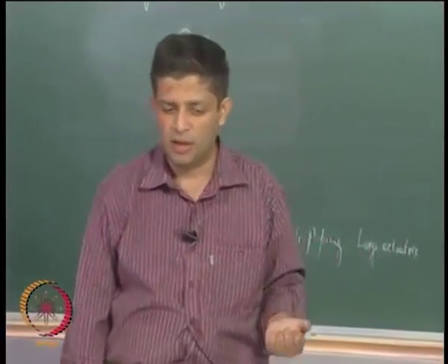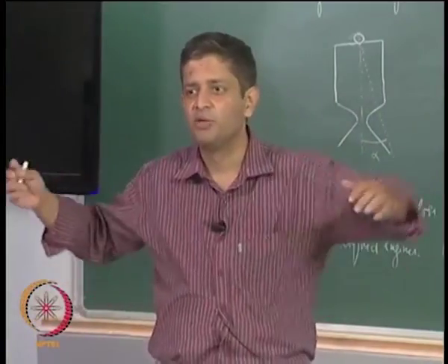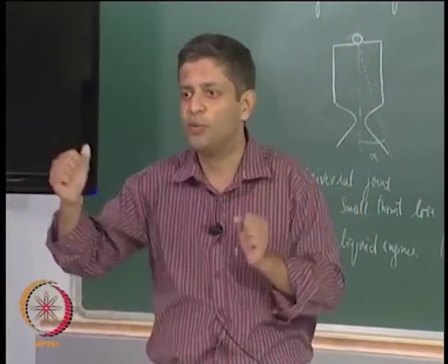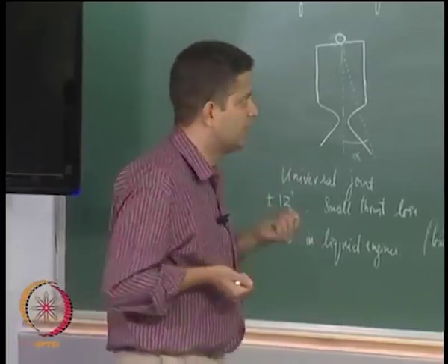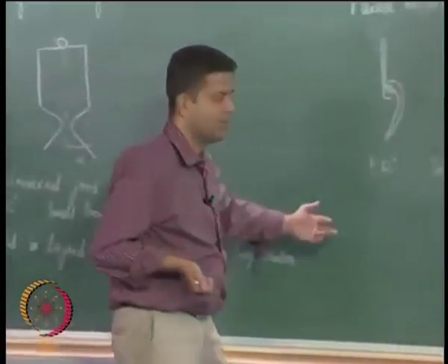Here you can use it in solid rockets primarily because you do not have to move the entire motor, you are only moving the nozzle, but still the actuation force required here is also quite significant.